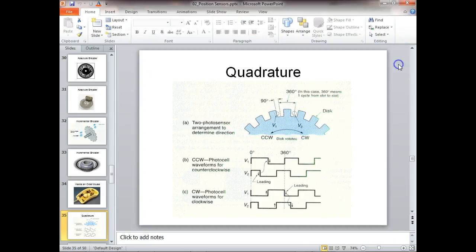Up until then, most of the speed systems that I had seen used tach generators, so it actually gave us a voltage that was proportional to speed. And these are incremental and quadrature, so these would have at least 2 channels, right? You understand? Might have 3 if it does an index mark, right?